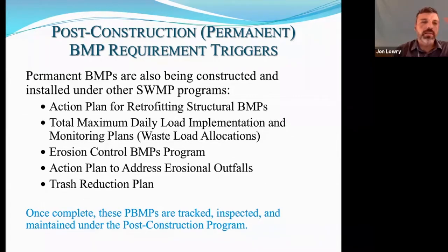So throughout the island, there are different watersheds, and where DOT roadways pass through watersheds that have total maximum daily loads, they're allocated waste load allocations. In order to meet those waste load allocations, DOT Highways often has to construct permanent BMPs to reduce nutrients to meet the maximum waste loads.